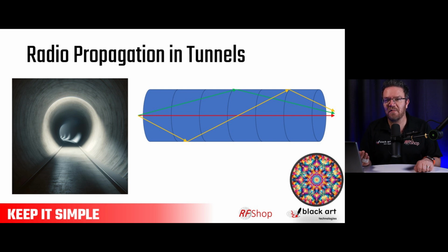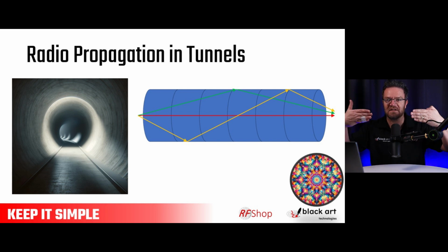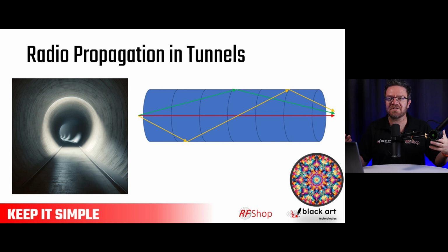That's an antenna fundamental that needs to be used to help make this at least much better than using linear to linear, because if you have two antennas facing the same polarization, when I launch here, by the time it gets to this one, it's mangled into a fraction in all directions. So you lose nearly everything because you can only pick up those bits that are aligned with your polarization at the receiver end.